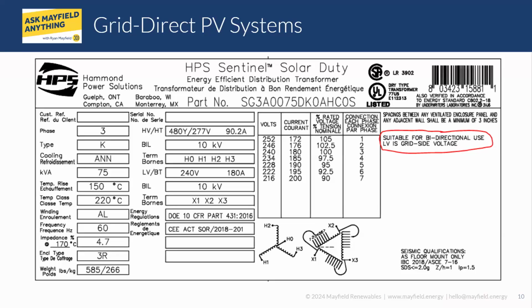Sure thing. That's important from a design standpoint to say it is suitable for power to run in either direction. Some transformers can utilize a compensated winding, which to my understanding is only suitable for power flowing in the intended direction, so you can see voltage loss when power is flowing back towards, say, the primary side.